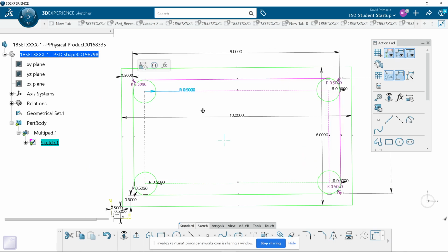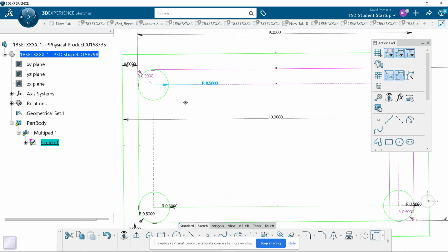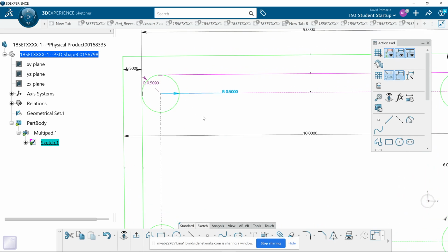So how I used to get... You want to run that for like a 3/8 or a 1/4 inch? Yeah, well, if I do a 3/8, this could take me forever to pocket this, because I want to hog out as much material as I can as fast as I can. So this 1/2 inch radius, I would modify it to 0.53. Does anybody know why I'd modify it to 0.53?